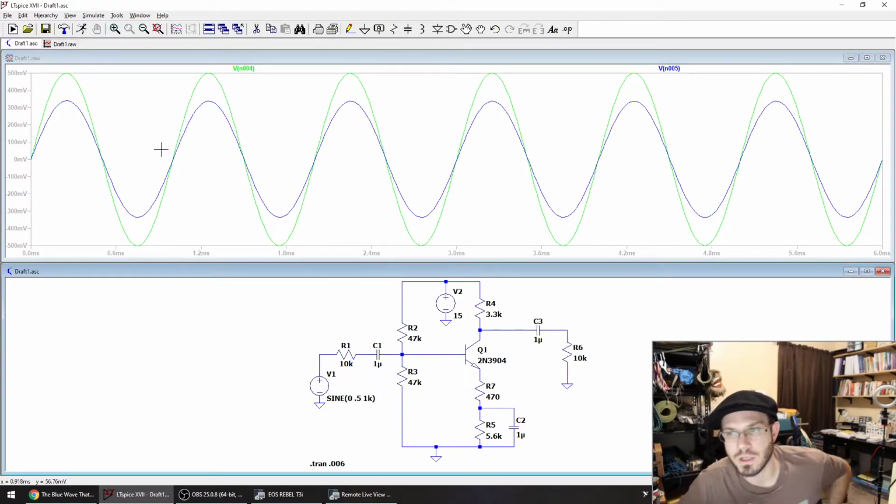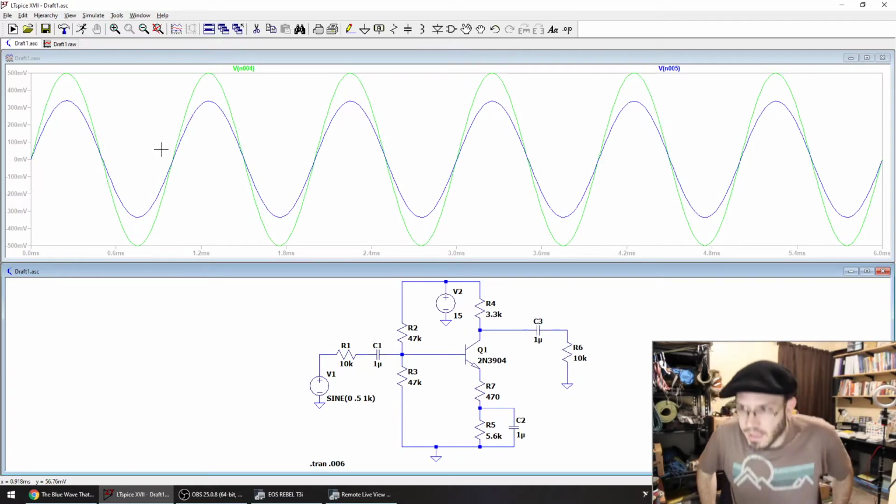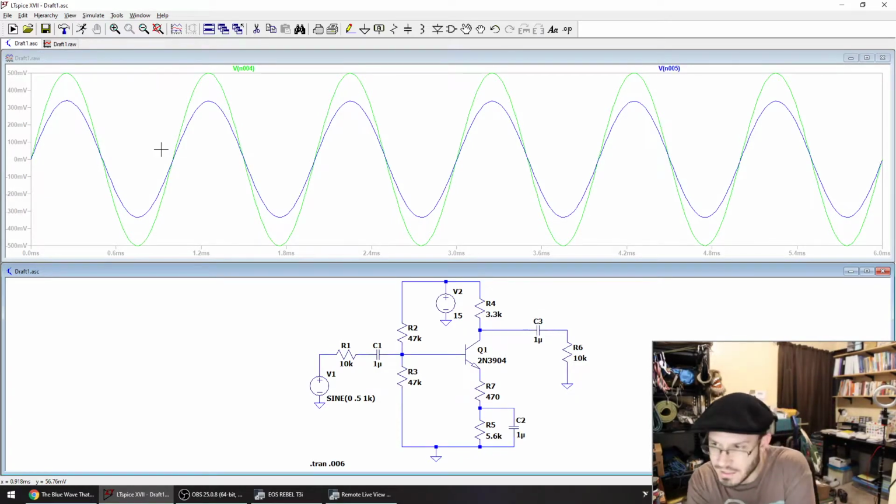Yeah, that's huge. Now, this is the type of thing that inadvertently people will connect up to an embedded system, to the input pin of a microcontroller, and then they'll wonder why their values are off by like 0.2 volts or something like that. So we do have to be mindful of our impedances.